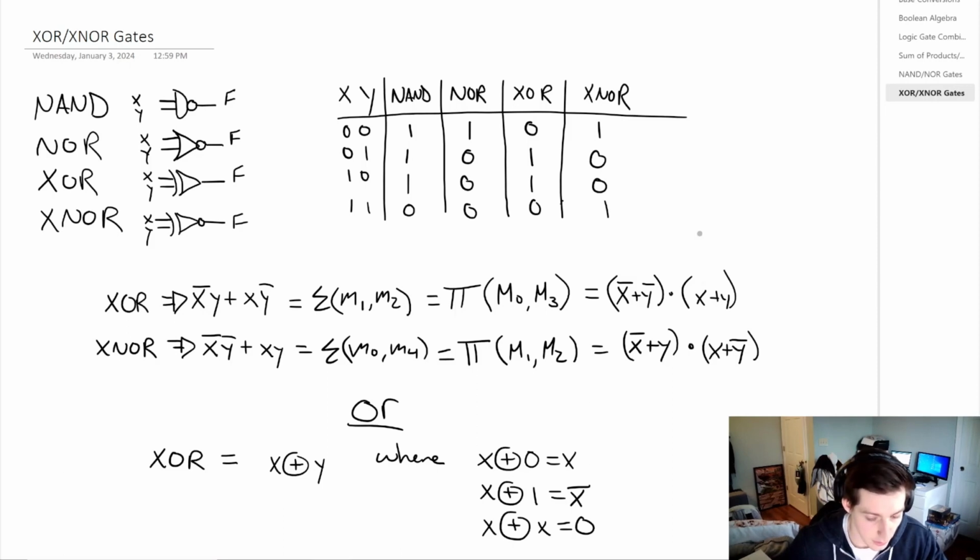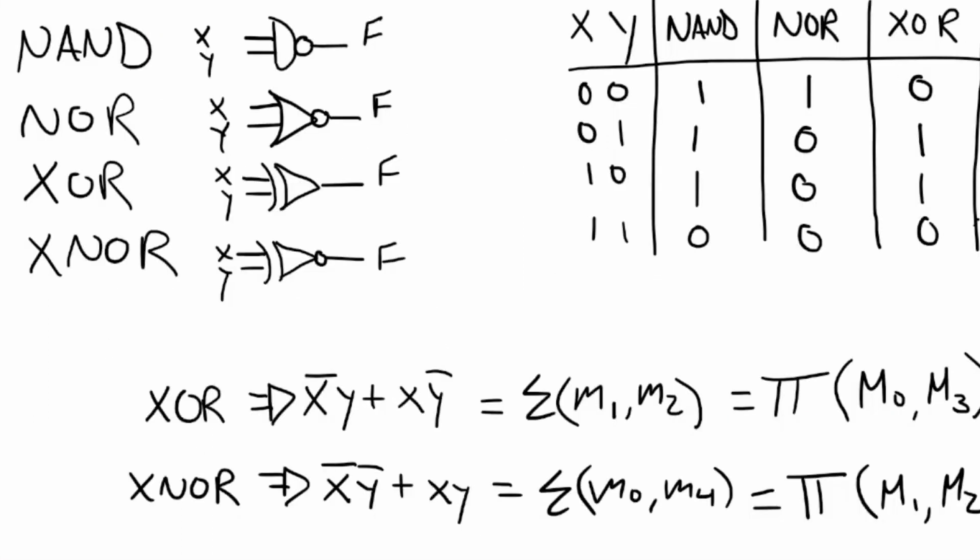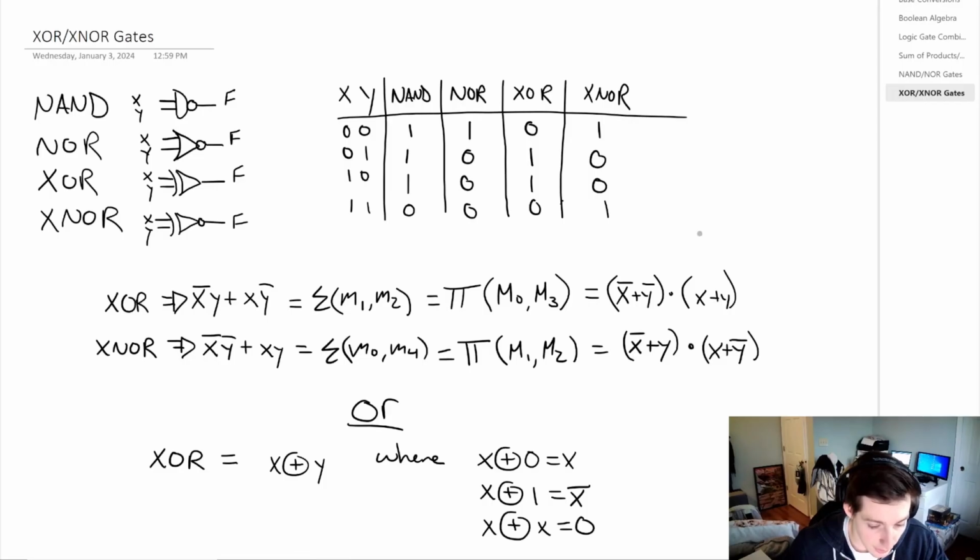In this video, we're going to introduce another gate, which is the exclusive OR gate. And we have a counterpart to that gate. Similarly, like we had with the AND gate and the OR gate, we have the exclusive XNOR gate. So the exclusive OR gate looks similar to an OR gate, except we have this extra little line here. And then for the exclusive XNOR gate, we have what looks like the exclusive OR gate with the little circle